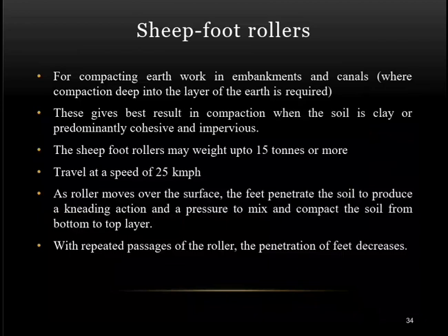Next one is sheep foot rollers. For compacting earthwork in embankments and canals where compaction deep into the layer of earth is required, it is used. This gives best result in compaction when the soil is clay or predominantly cohesive and impervious.